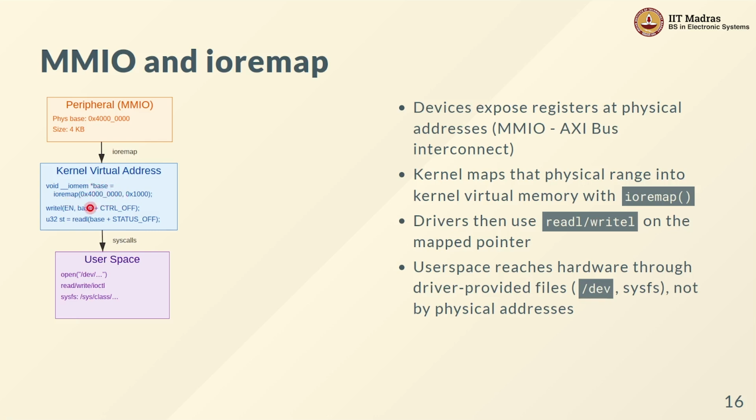So why do all this rather than directly talking to this? Because at the end of the day, I need to once again use specific system calls, right? Write-L and read-L. And by capturing this pointer out here and using it, it allows me a certain degree of control, right, over how exactly I can communicate with these specific locations, right?